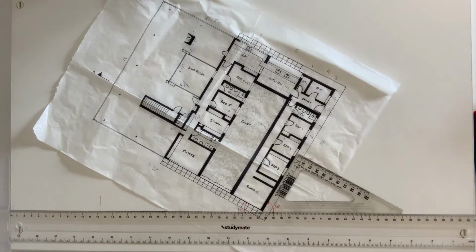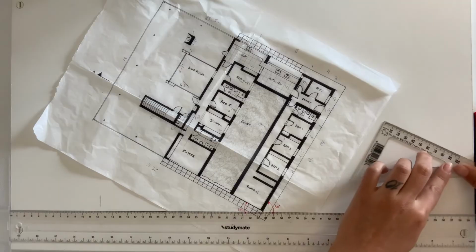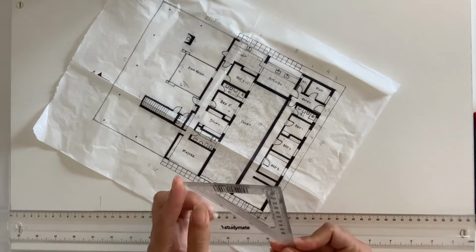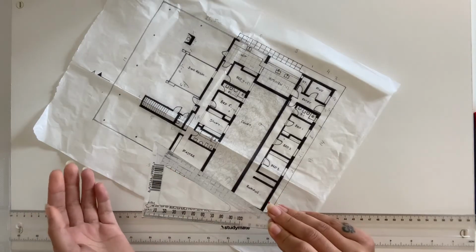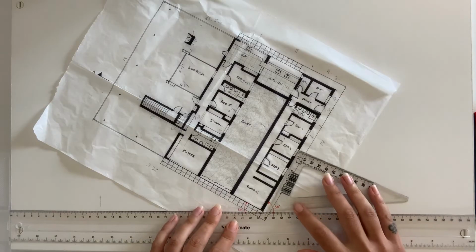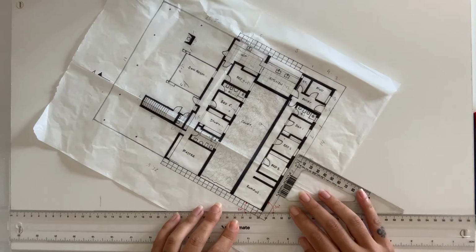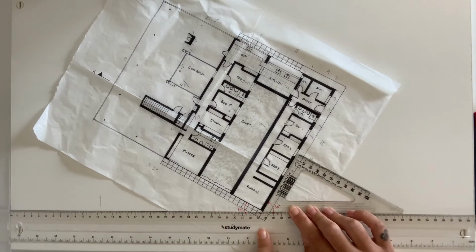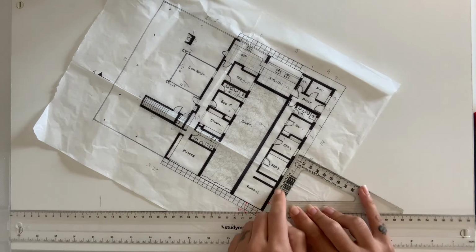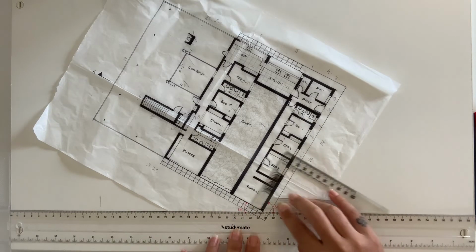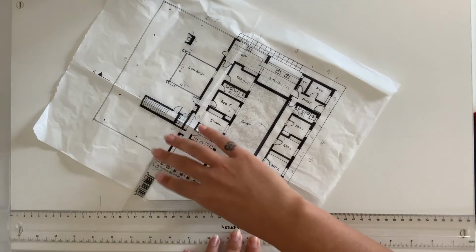it's also handy. Usually they come in all different sizes. This one is a bit smaller, which isn't very practical. If you can get your hands on a larger one, it'd be a lot more helpful when you're drawing the longer walls. So you just slide it across the T-square and you allow the external wall to be in line with that angle. And that's how you'll check these angles to make sure that they're accurate.